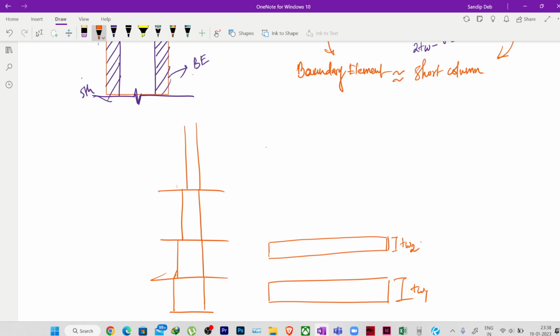Then you have to check whether the thickness we have provided, and the slope that we will be providing for the bar, is meeting the requirement of SP 34 or the codal provisions or not. If it is not, then you may have to provide more thickness than required. Then again at the next floor we may reduce the shear wall dimension.